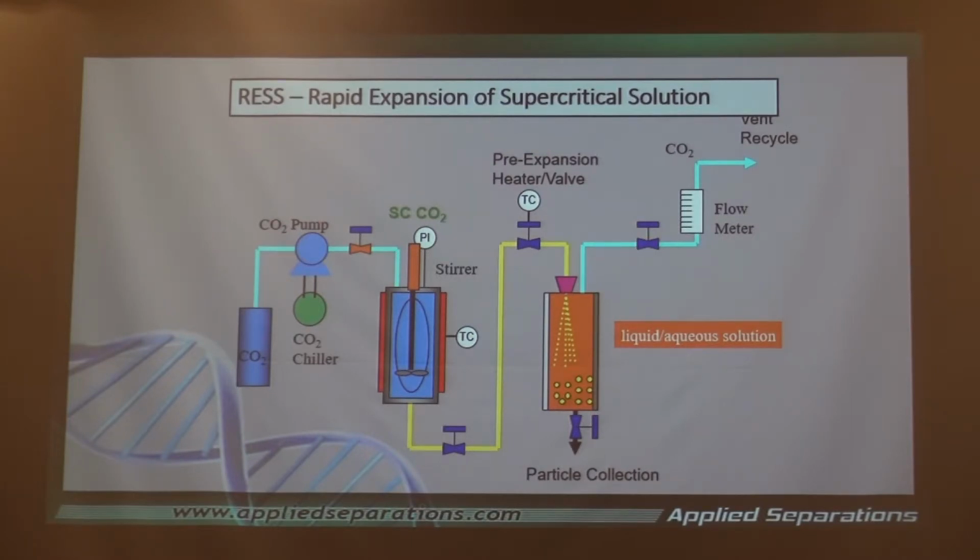So you may think you're going to be making the material at, let's say, 100 nanometers, and actually it agglomerates together, and you have something that is 20 microns, as opposed to 200 nanometers. They agglomerate very easily. This is one of the reasons why you disperse them in a liquid, because they will not agglomerate as quickly.